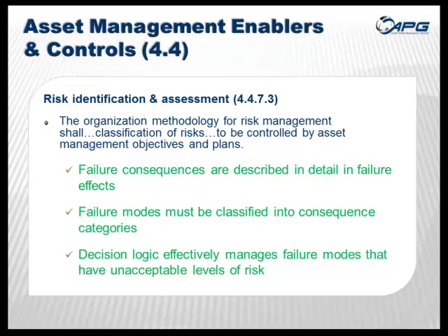As I stated in question 5 of the RCM concepts, one of the key questions is just understanding what the consequence of a specific failure is. When a failure occurs, will it impact people? Can it injure or kill someone? Can it damage the environment? Or at the other end of the spectrum, is it simply a failure that has just the cost of repairs as consequence? Identifying those will help to classify the risk associated with the given management policy, and thereby also help us to achieve our objective of controlling the management objectives.